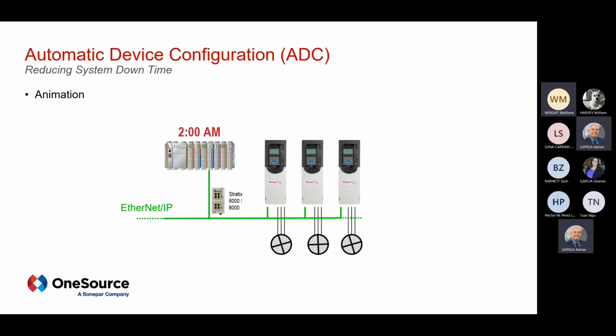Next, install the new drive. And depending on how the system is set up, if you're using a managed switch and you have it set up for IP persistence, where the drive will be set for DHCP, the switch will automatically assign the IP address from that particular port to the drive. You don't need to configure an IP address manually if you have a managed switch.